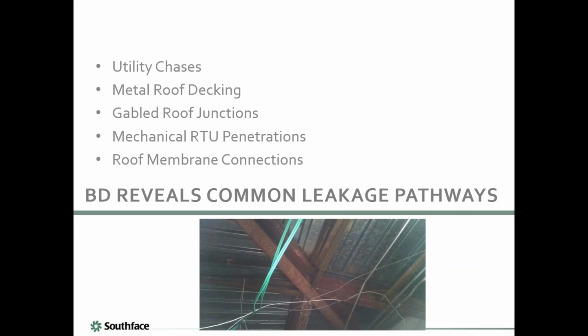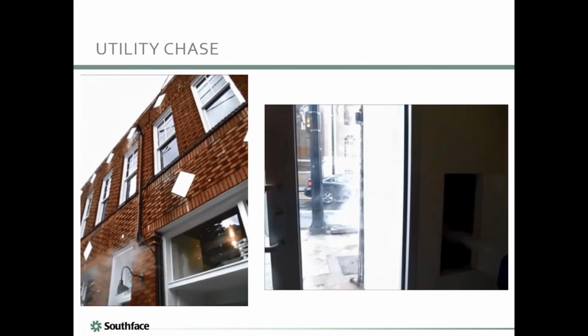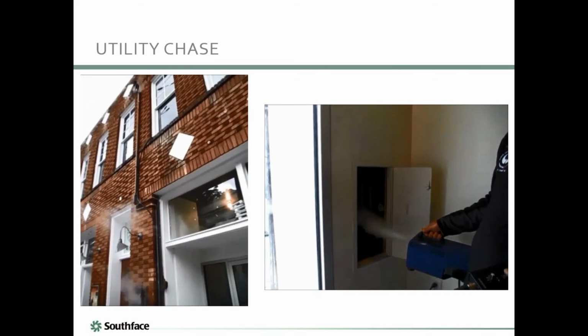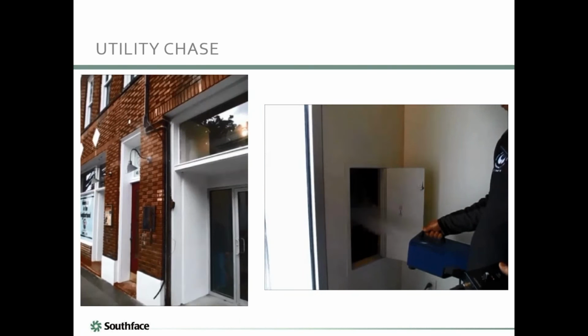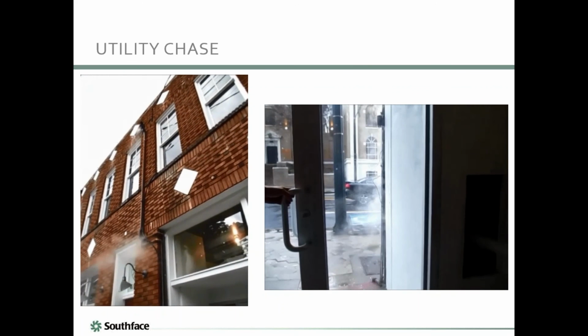But I remember there was something kind of neat. We tested two block buildings that it just happened, one was in North Georgia, one was in Atlanta, and we tested them within a week. And they were roughly the same square footage, I'm going to say around 4,000 square feet. You helped on one of them, and one of them came in pretty tight, and the other one came in unbelievably leaky. A lot of it was because the leaky one had undergone some renovations in its life. Lots of holes had been busted into the CMU, and lots of leak paths. But unfortunately, you can't just say, oh, it's a block building, it's going to be tight. We could not recommend that you make that assumption.